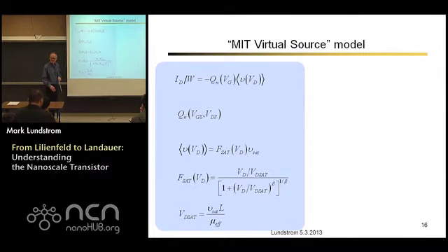That's leakage. It means we have to be a little more careful, use the exact solution or something, but we can do that. The average velocity is just this empirical saturation function times Vsat. We just have to tweak the parameter beta a little bit, and Vd sat we know. So that's a model that works really, really well. So I've just gone through the 5 parts of that model.